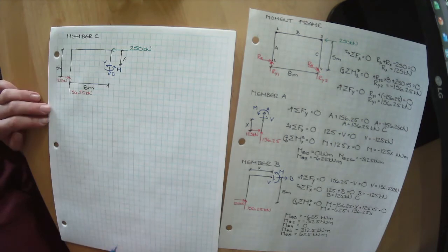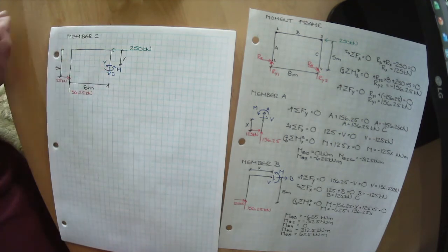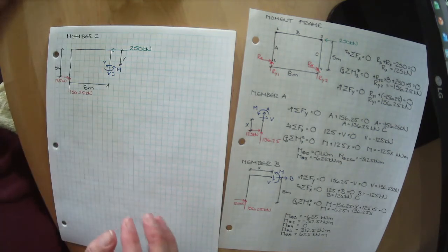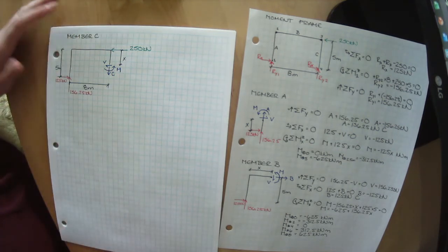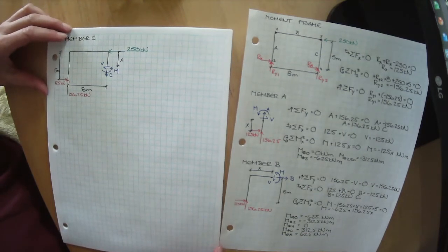So there we go. We've got internal placeholders for shear, moment, and axial load. If you're wondering why we didn't use axial load placeholders in the ones we did last week, there was no load and our reaction was 0, so they all would have worked out to be 0. You could have used the placeholder for the member for an internal axial force, but they all would have worked out to be 0.